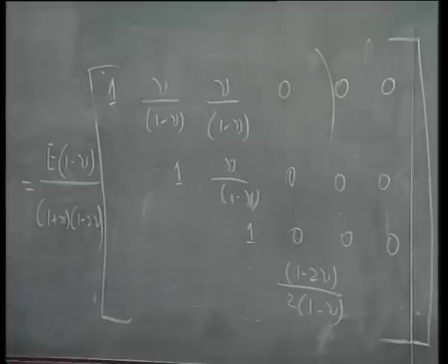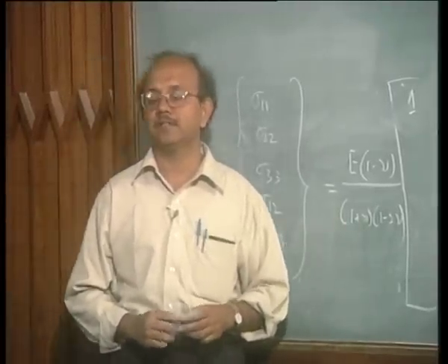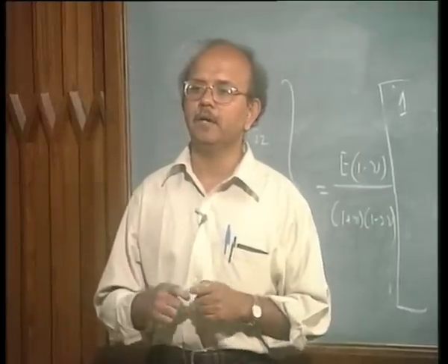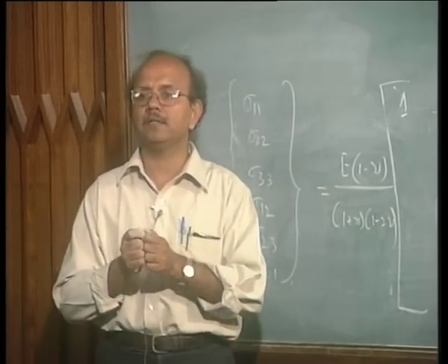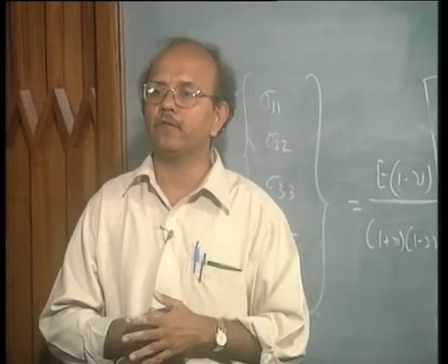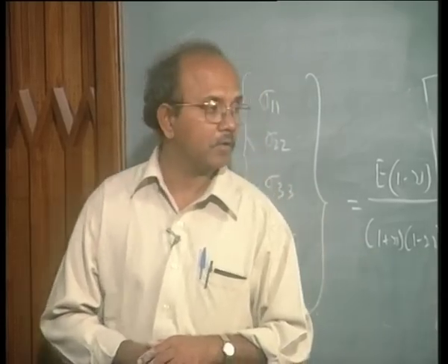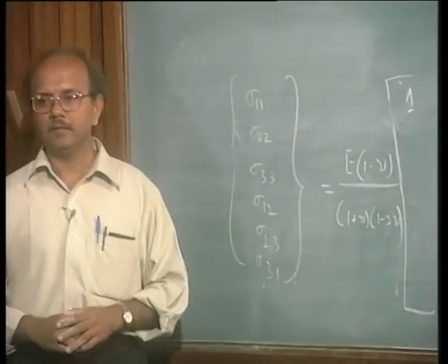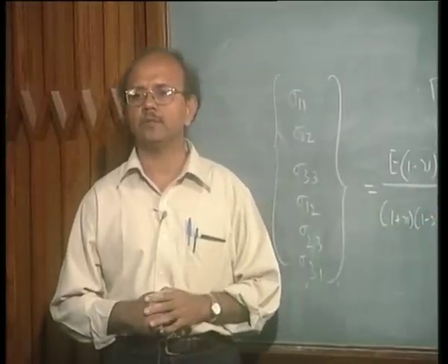One more question I asked before we go to other simplifications: can nu be above 0.5? Yes, unfortunately yes, and many codes do not even accept it. Say reinforcements in tires, some of the nylon reinforcements, are believed to have nu even above 0.5. So many codes do not even accept it. There are problems from that point of view also. Well, let us not worry about that, those are material aspects. Let us come back and look at whether we can simplify this 3D situation into a 2D situation.